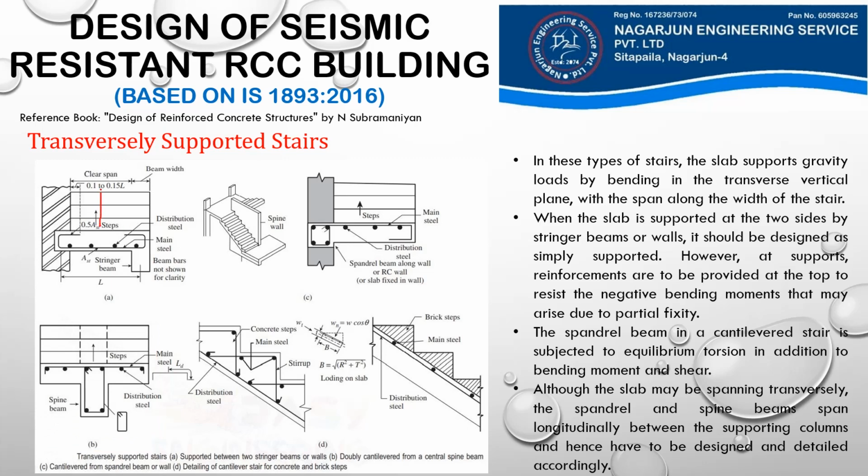The steps are in this direction, that is perpendicular into the plane of this paper, if you think about this, and then our steps are here, supported on beam on one side and walls on the other side. So when certain load acts on this stair, then our staircase deflects in this pattern. Similar is the case here for this number B of this staircase resting on a spine beam. When load acts on our staircase, then it deflects somewhat like this.